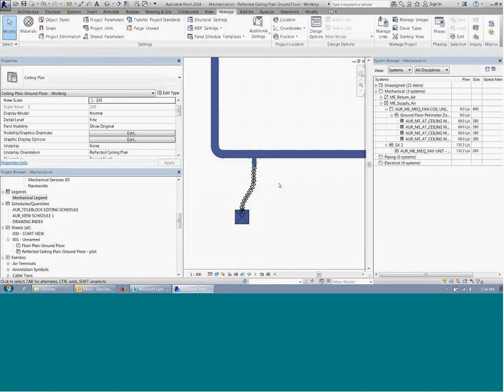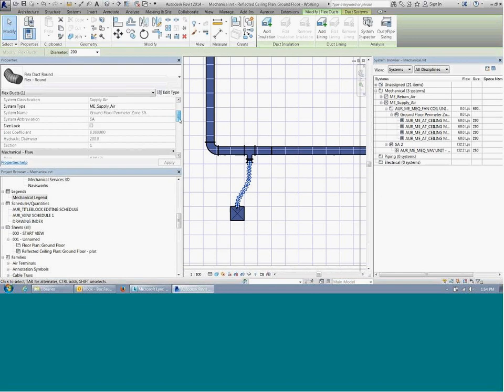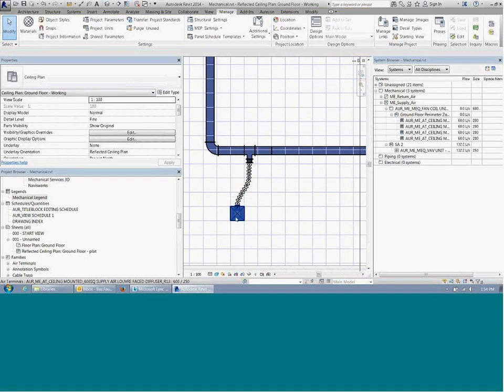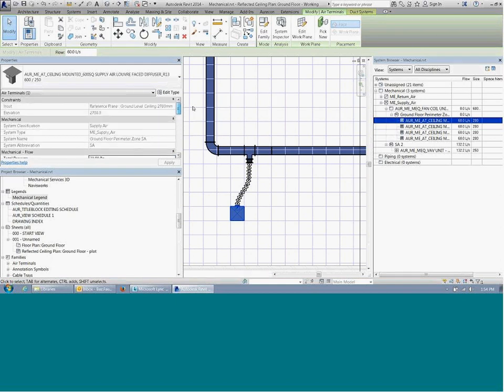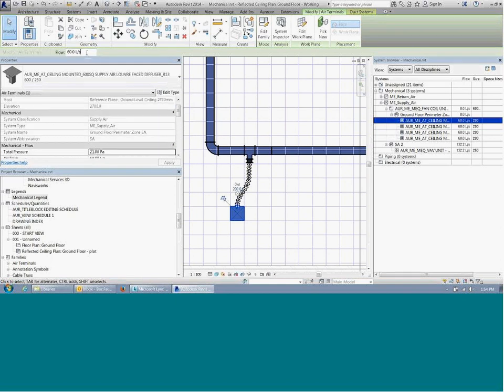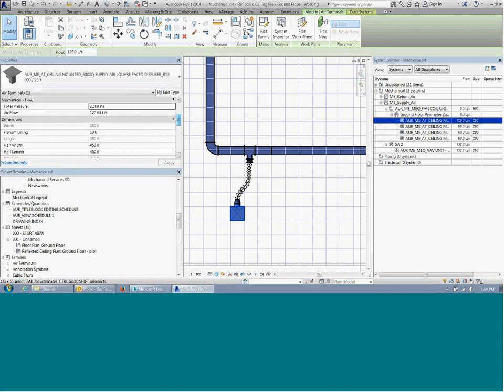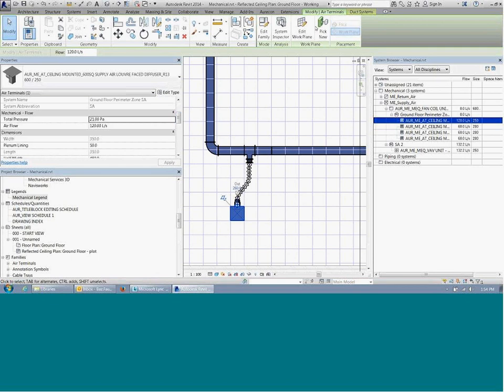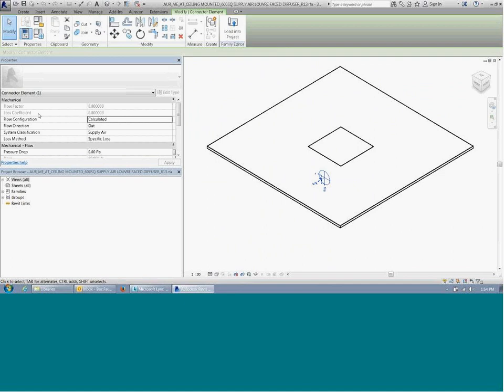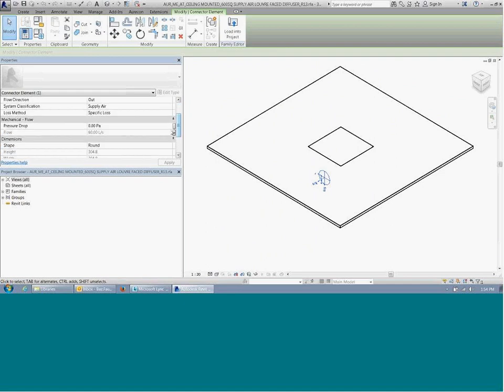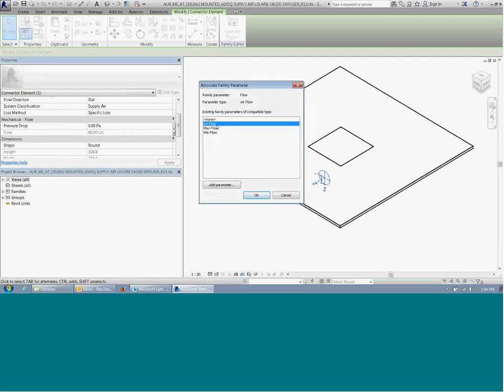Still got no flow going through. Once you get the flow parameters, then you can tag it. Is that right? Tag it, but then the duct sizes usually will go lower near the equipment, and as it gets closer to each of the grills, it automatically sizes it to the airflow. Yeah, it'll get smaller and smaller. That's Revit.